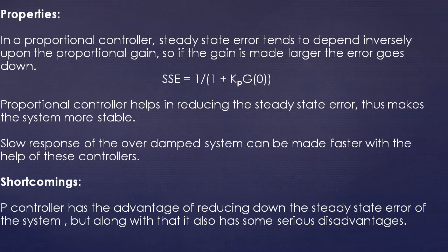So if the gain is made larger, the error goes down. This type of controller helps in reducing the steady state error, so it makes the system more stable.